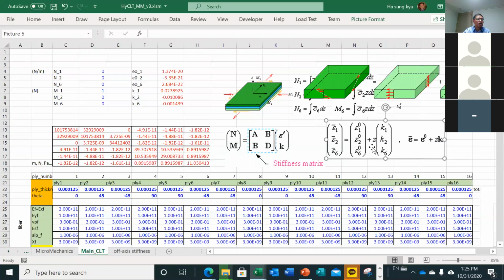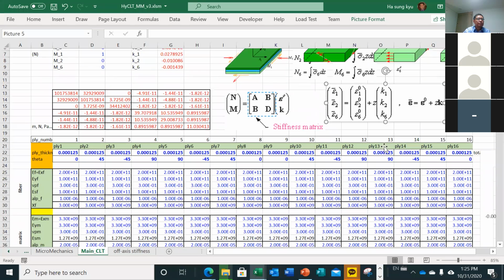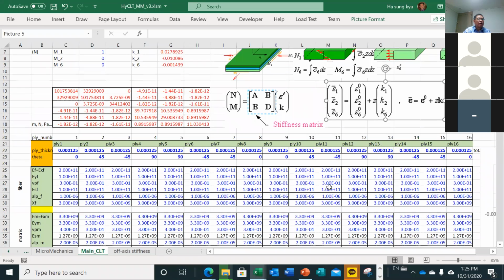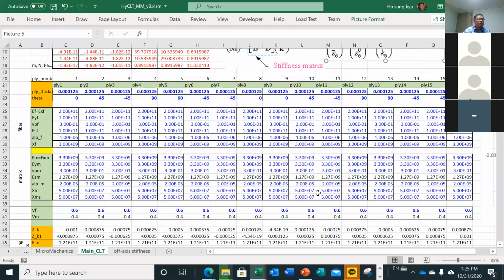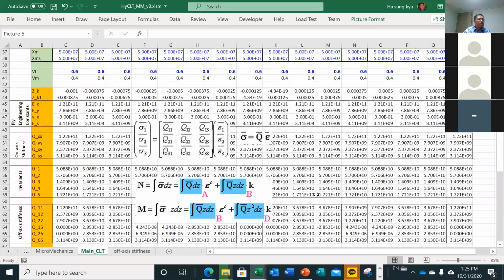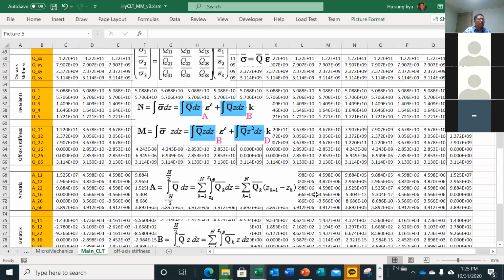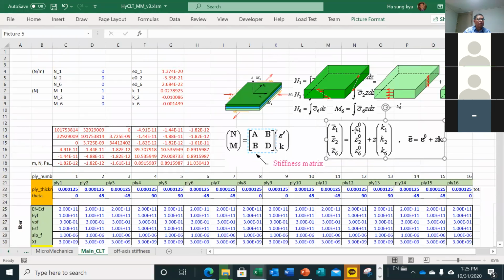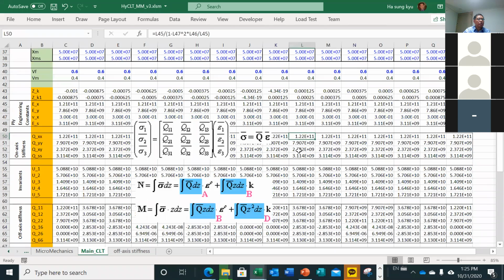That is an assumption in most of our structures. Most structures, which are relatively thin through the thickness, will follow this behavior. The assumption is that strain is linearly distributed through the thickness. This is a very important observation and it captures the behavior of this strain quite well. So we put this equation to here.